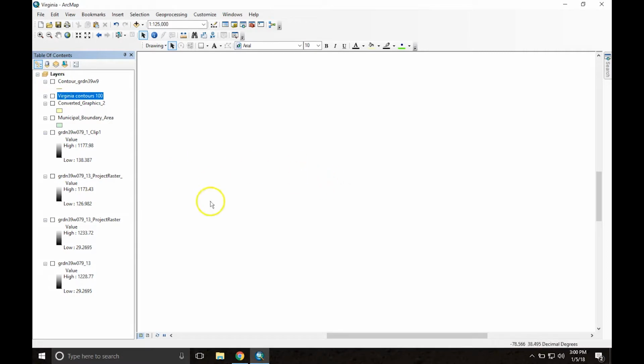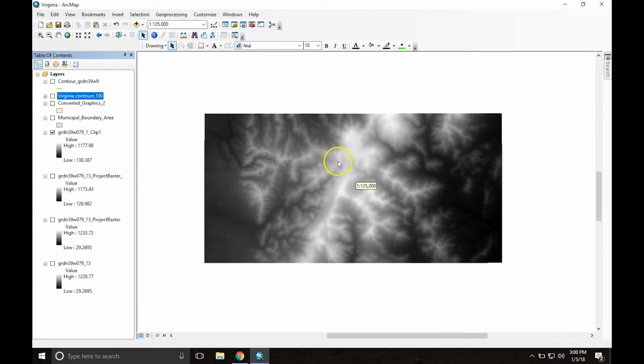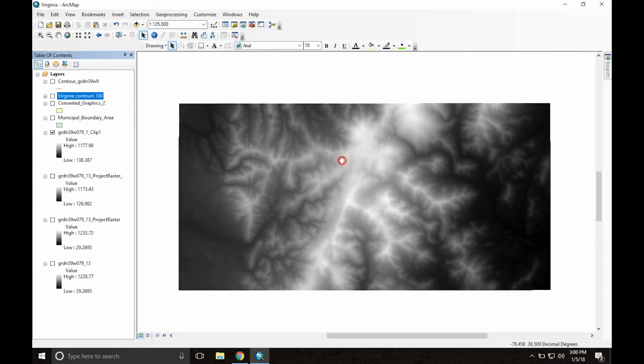But before we get out of here, the other thing I'm going to do is there's a command in Rhino called Heightfield, and what it actually does is it generates a surface automatically and directly from a DEM image or from any sort of grayscale image. We're actually going to save this DEM as an image, and then we'll use that in Rhino as another way of generating this surface.